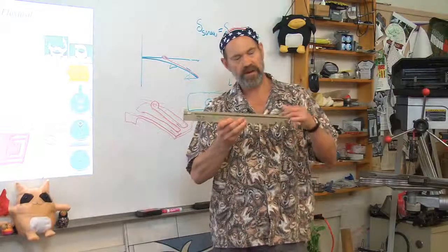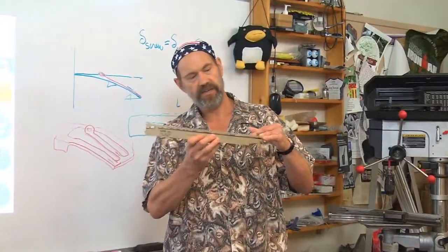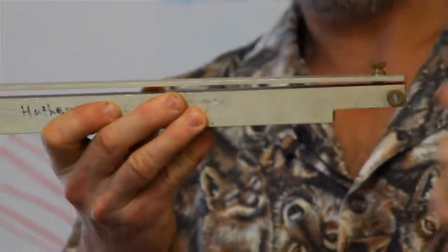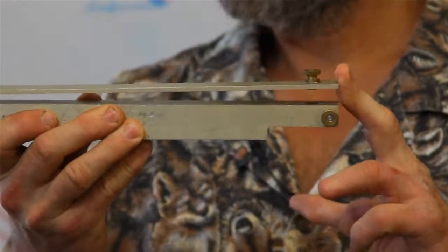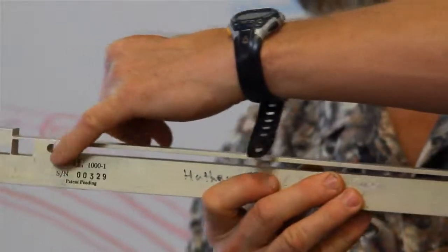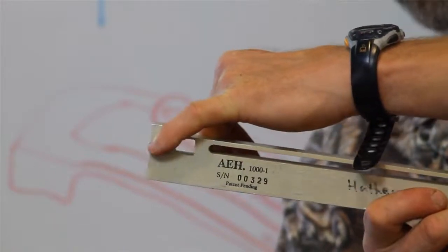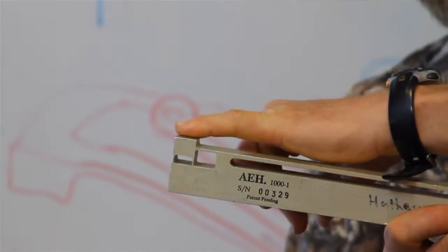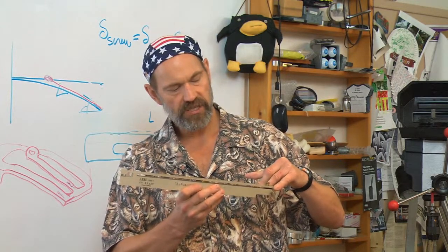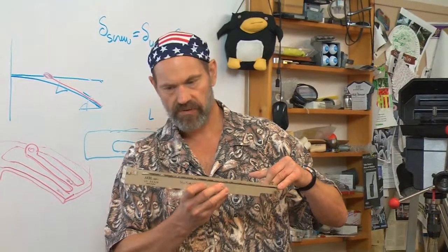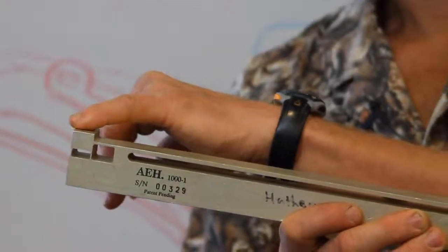Here's another flexural bearing which is used in a transmission ratio. My friend Nelson Hathaway invented this design. When I move this structure up and down, there'd be a micrometer here where I could control this motion to the thousandth of an inch level, it's creating a strain field over here that causes this surface on this little 4-bar flexural linkage to move 1/1000th of this motion. So in other words, if I move this here 1 millimeter, this stage here has gone 1/1,000,000th of a meter in motion.